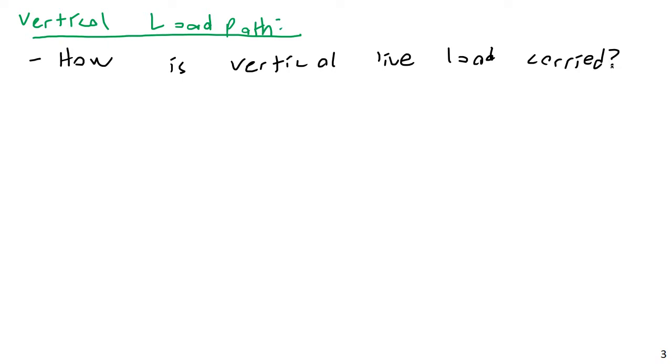Well, we of course know that live load is the combination of really everything in a structure that moves around, that can be picked up and moved around, that will occupy different places at different times. In this classroom, all of the live load is yourself, myself, the tables, the chairs, all of our belongings, coats and backpacks and things like that. All of that stuff is live load.